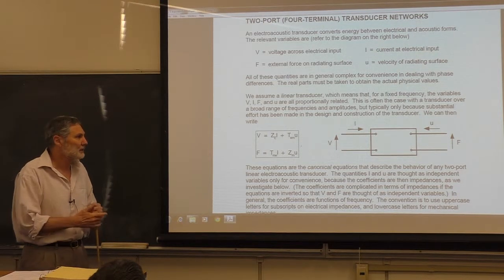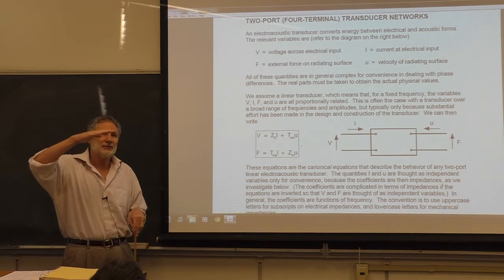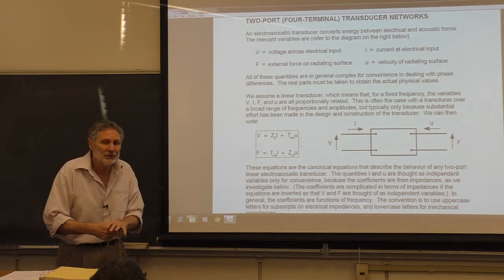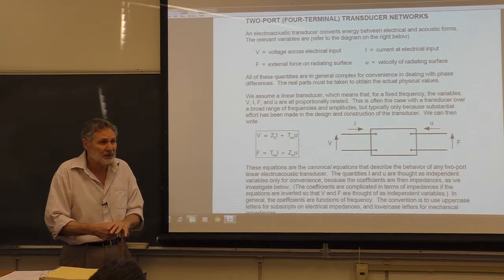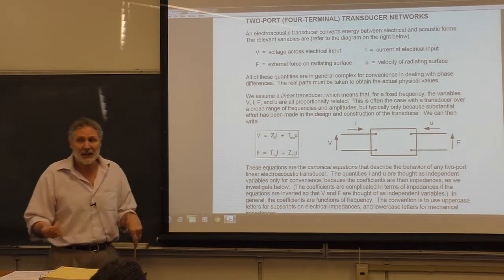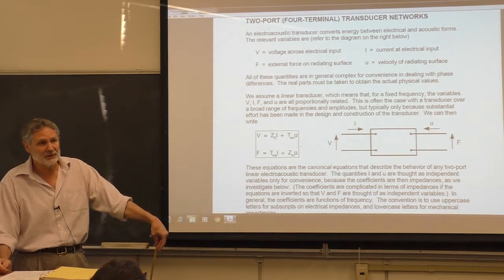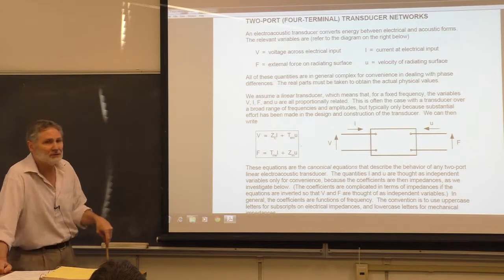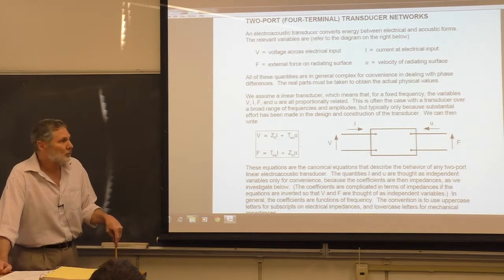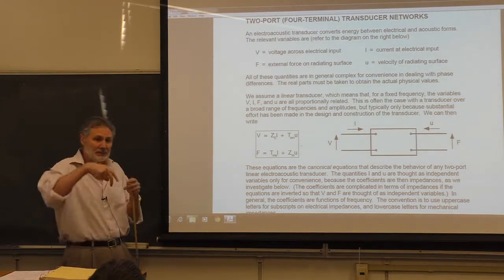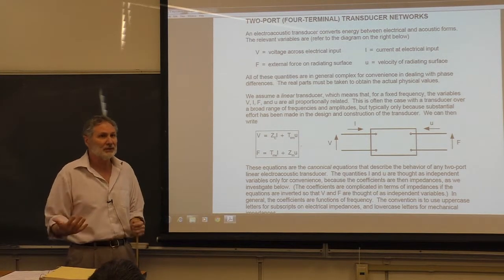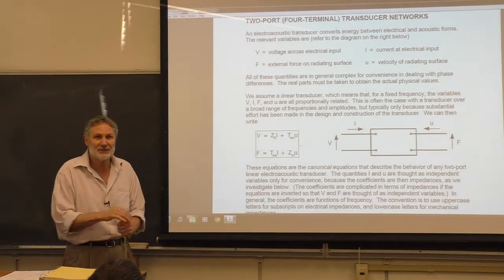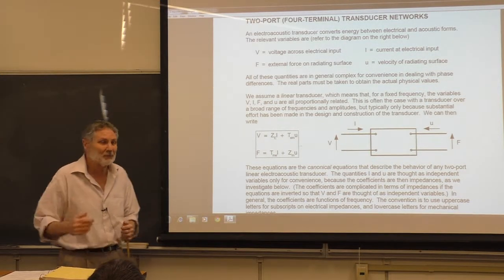Often you want to find out, like for the surface wave height demonstration, you want to measure that surface wave height. So once you know the sensitivity, if it's linear transduction, and it's flat, independent of frequency, which it is in that case, there's just one number you deal with. It's the sensitivity. There's so many millivolts per millimeter. So once you measure electrically with the probe there, once you measure the millivolts, you just take this sensitivity and you immediately find the millimeters. That's the goal of transduction, right? That's the basic goal.